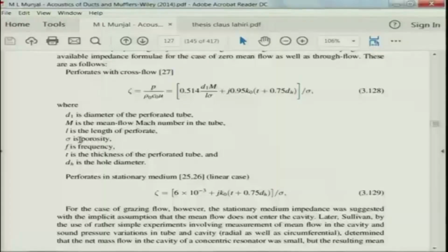At the same time, acoustically the performance will be very similar to that of an extended inlet and outlet muffler. It would not affect much acoustically, but it has a very good influence on reducing or eliminating the separation noise that would otherwise occur.